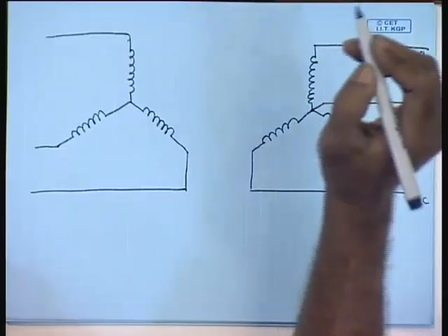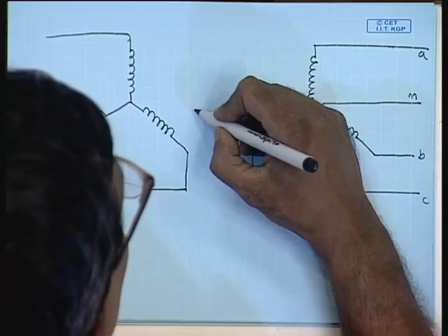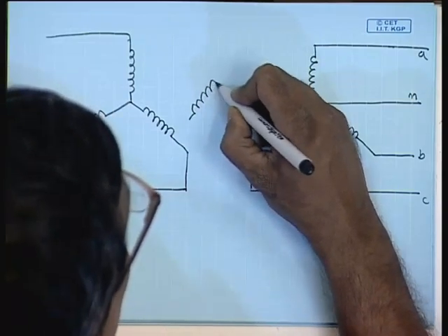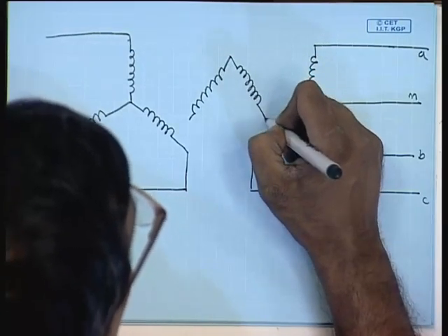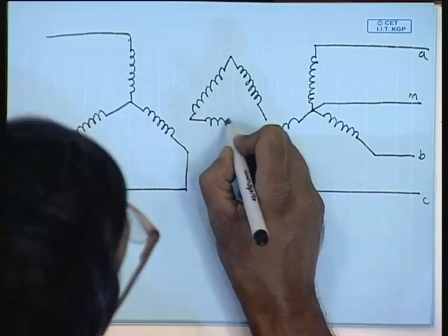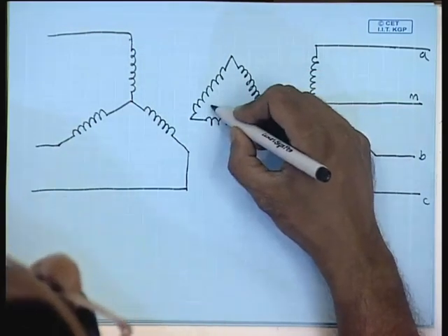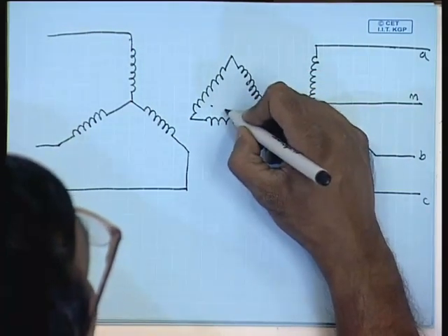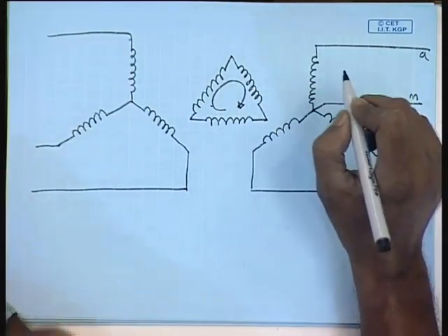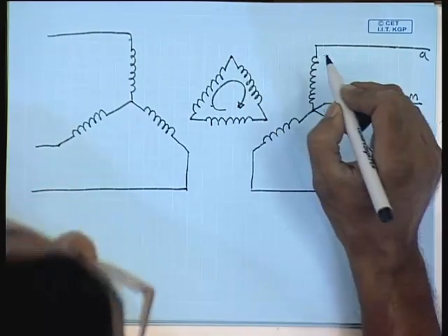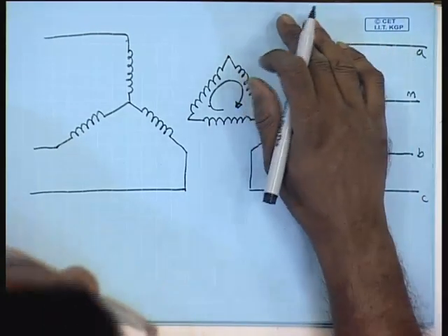This can be done by a delta connected winding, a third delta connected winding. When we provide a delta connected winding like this, then the co-phasor current, the zero sequence and the triplen harmonic currents can circulate within the delta winding, thereby cancelling the co-phasor MMF completely.